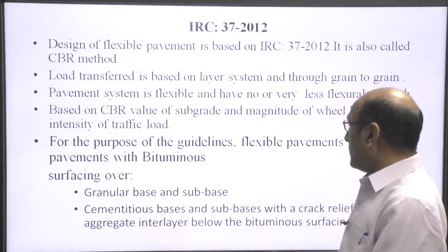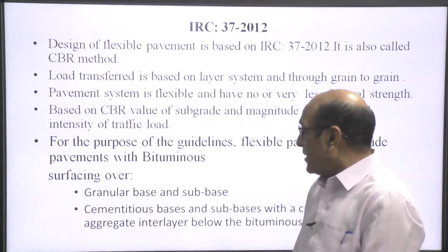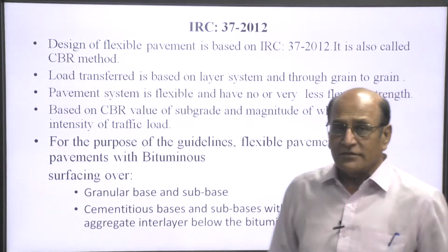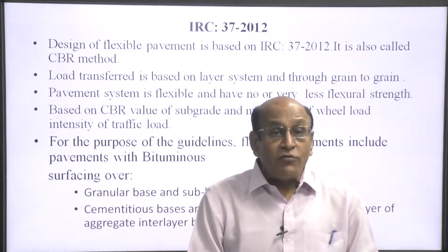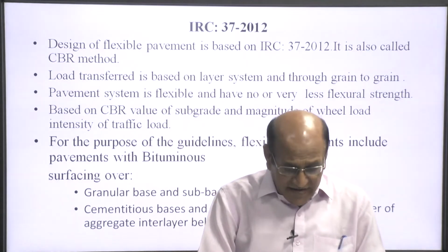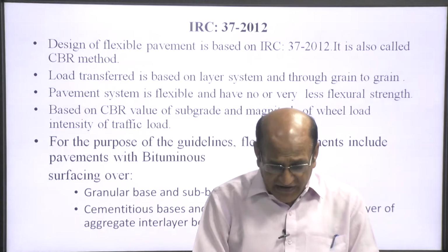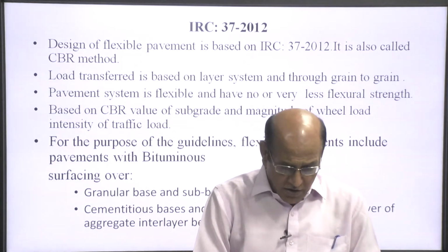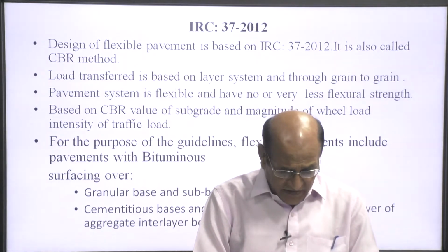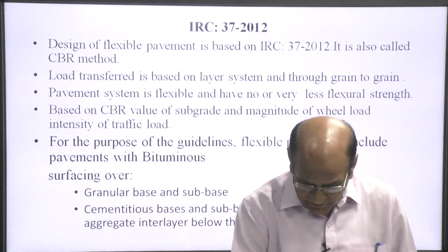For the purpose of guidelines, flexible pavements include pavement with bituminous surfacing over granular base and granular sub base, cementitious bases and sub bases with a crack relief layer of aggregate interlayer below the bituminous surfacing.